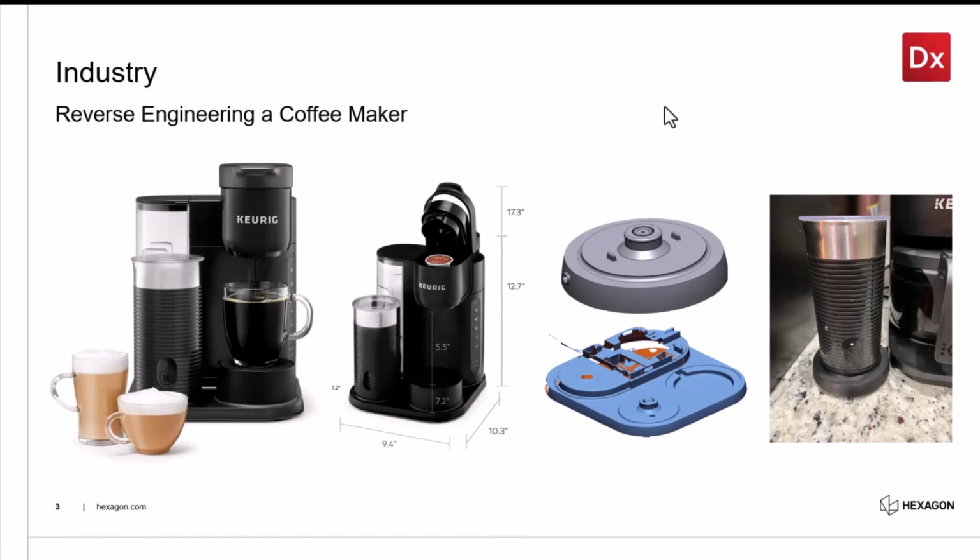So today's session is just talking about how I went about scanning this part, because I scanned an assembly and I assemble it together. And then for the reverse engineering part, the key thing that I like about that workflow is that I modeled from an assembly of scans to make a condensed part for additive, for printing, right?